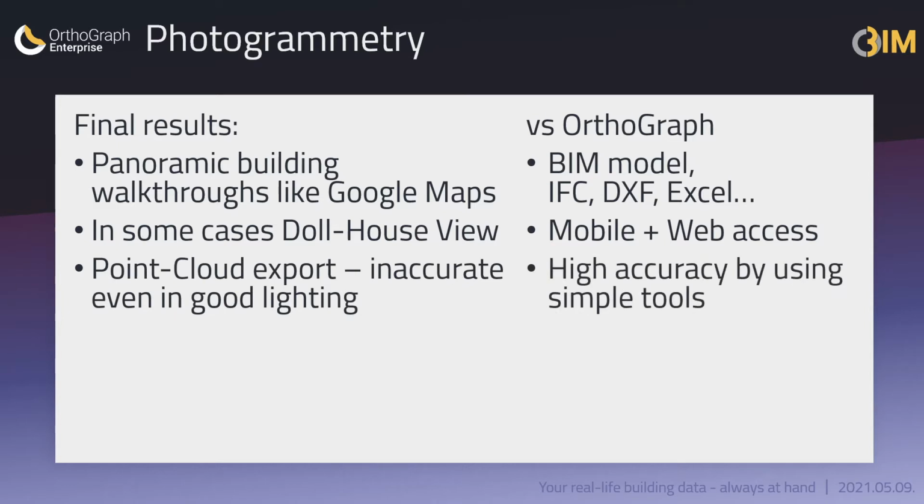There is a big problem where the point cloud can win against today's photogrammetry solutions, which is accuracy. 2% inaccuracy might result in the loss only on rental fees during the 30 to 50 years of building life cycle, which is comparable to the total construction cost of the particular building. And we speak about 5 to 10 cm inaccuracy, but let's go back to this topic later.